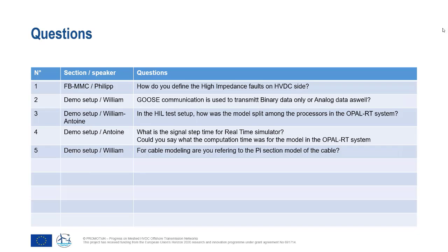dynamics, and the protection. The computation time of the real-time simulator depends on the load of the models, but the main aim is to have a computation time faster than the model time step. Otherwise, you are not in real time. And for that, you split. You can see in HYPERVIEW, the target analyzer that I presented, the execution time of each core. It will depend on the model, but you can split your model into each core and see their real execution time.